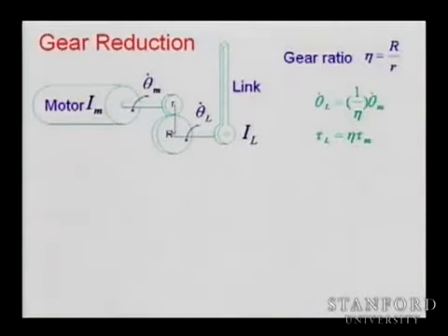Okay, is the motor going faster or is the link faster? The motor. So the gear ratio is reducing the speed, the link is going slower. So how much slower? 1 time, 2, twice, 3. He said like 2. Yeah, it is 2. I was worried. Okay. So the gear ratio is really R divided by the other R, the smaller r. So that's your gear ratio. And the link speed is smaller by that ratio than the speed of the motor, right?